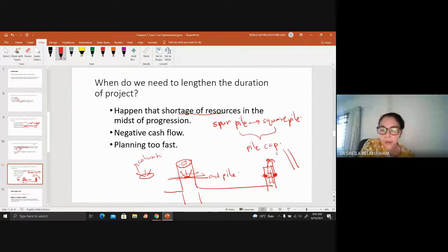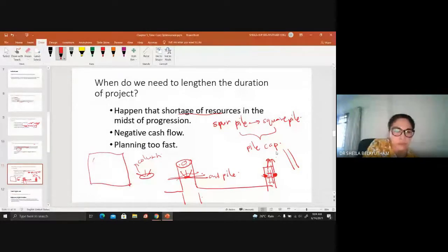Normally you'll be given a piling plan, which requires you to have a pile here, pile here, pile here, pile here. Usually for a spun pile, you can get it right, even if you connect 2-3 piles together, you can get the point nicely. But sometimes with square pile, we try to drive here, but if it's broken at the top, you can't connect two piles together.